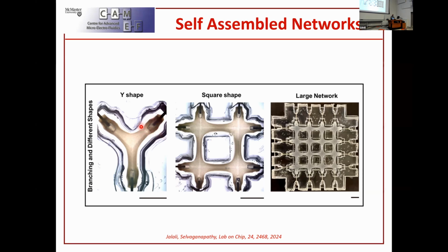And by using this self-assembly process, what he has done is, these are plastic connectors that you can buy at McMaster-Carr, for instance. And what you see is that because it is self-assembling and shrinking, it imposes a compressive force on the plastic part and creates a tight seal. We can actually apply pressure and perfuse it. It won't go to a very high pressure, but nevertheless, we can apply a pressure to perfuse and it won't leak, right? And so this assembly is very nice in terms of interconnection to plastic devices and creating a very tight seal for transport related studies.